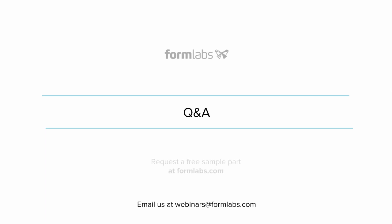Gotcha. Well, hopefully we answered that in detail. I will add a little bit more to that answer though, because it really comes down to what support size you use. If you use really large support points or way too high a density of support points, then it gets kind of difficult to remove them all. It can also mar up your surface. But as you use the printer a little more, you start understanding what you can get away with on support structures. And as you saw on the part I did, 0.55, so basically 500 micron diameter points at a 0.9 density, they came off really, really easy, and they left basically no artifact behind. So that's something you get used to as you use the printer a little bit.